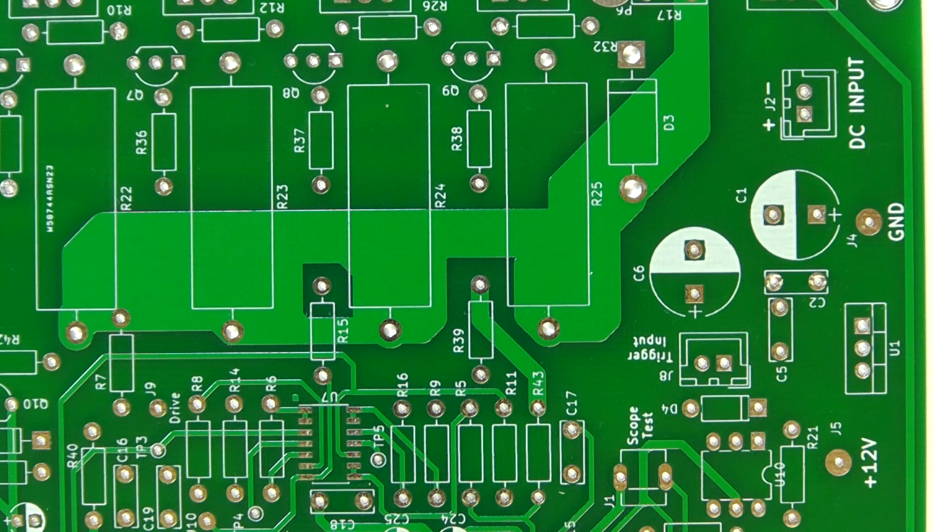you've got more current flowing in certain areas of the PCB, and then that causes this fluctuation you see on the display. It also causes a little bit of problem in terms of the calibration on that leakage current that we mentioned. So what we're going to do to resolve that problem is add additional grounding with some additional copper wire onto the reverse side of this PCB. So let's have a look at that.